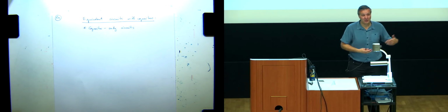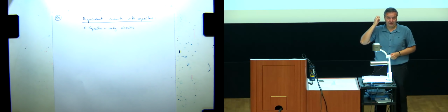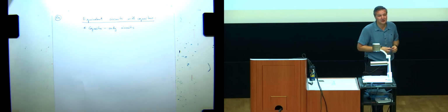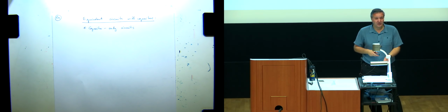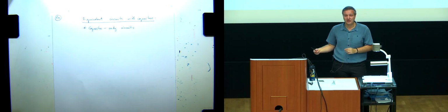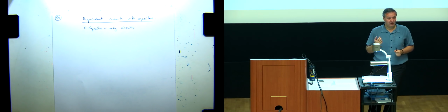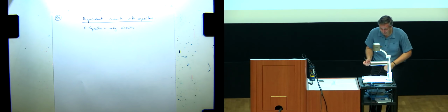So it becomes a little bit yucky. People do it, and if you do Laplace analysis, that will all become a linear system of equations. You'll do that in the follow-on courses. But here, if we assume capacitance-only circuits, we can use the derivative of voltage in all these equations, and it's just linear equations, just like we did with the 7-step procedure.